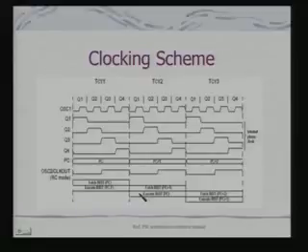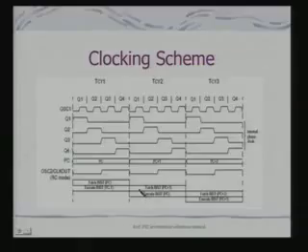A data movement in terms of bus demand, data movement from your register file. That movement would take place on your data bus. So my program bus is free, so I can fetch an instruction. What am I fetching? I am fetching the instruction at PC plus 1. Similarly, when I am fetching the instruction pointed to by PC, I am executing the instruction pointed to by PC minus 1. This is how the instruction execution takes place, and what you really realize is that in one cycle, one instruction gets executed. Is this clear?